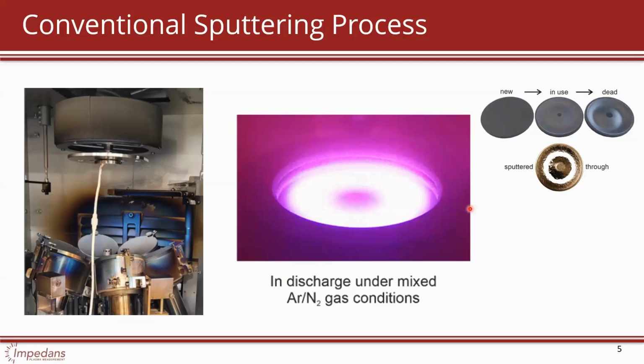Just a little note, if you are using a standard plasma chamber that's not sputtering, just CCP, whatever, you're still sputtering, okay? If you have an ICP tool and you have a ceramic dome, there are actually large electric fields on those coils, and you are sputtering away your ceramic liner over time. It makes it rougher, like you can feel the roughness.